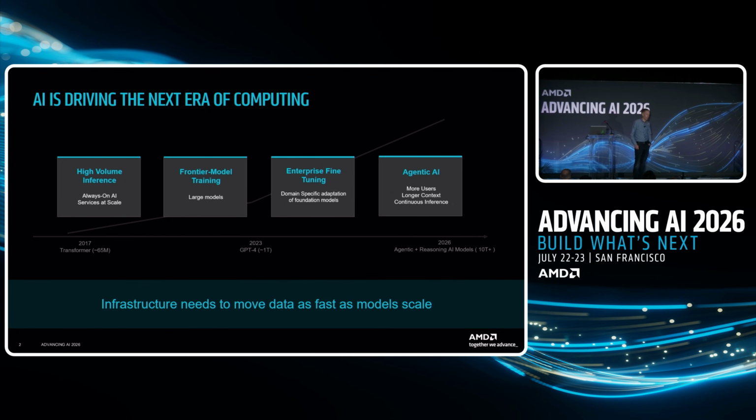I'm also talking about things like the context size and all of that stuff. And what it comes down to is, in order to solve the big problems, you need multiple GPUs. And having a very high-performance interconnect to connect a large group of GPUs together allows you to solve these problems with higher performance and or higher efficiency. That's why we need a scale-up interconnect, and that's why it needs to be a large scale-up domain.